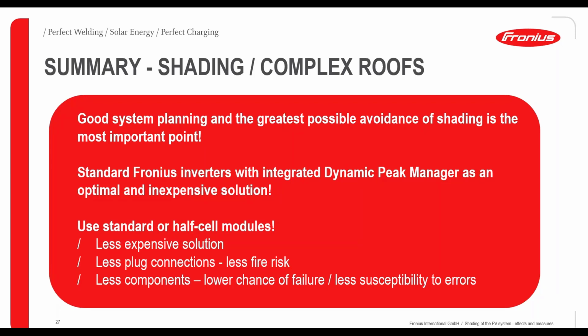The second thing I want to give you is that standard FRONIUS inverters with integrated dynamic peak manager are a perfect, optimal and inexpensive solution for most of the usage. Only when there is really, really strong shading and so on, you would need a different solution. But for no shading, for low and for moderate shading, you're perfectly fine with standard modules and standard FRONIUS inverters with integrated dynamic peak manager.